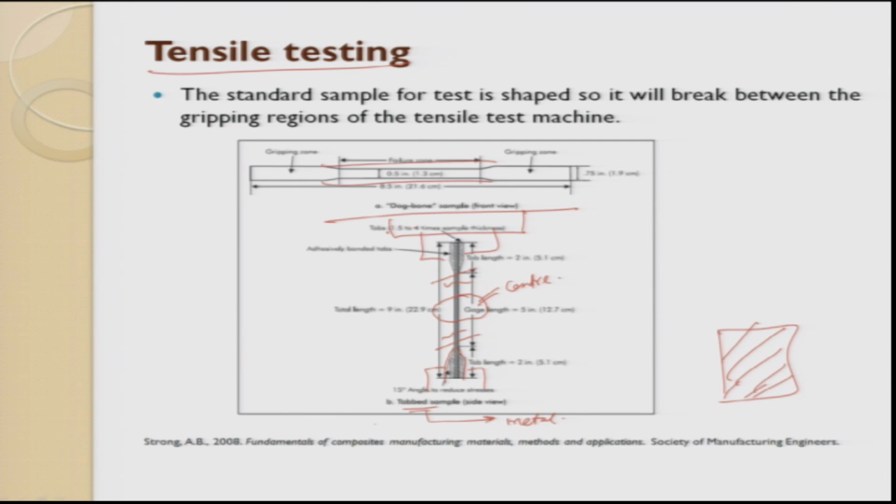The other way around is you use the chamber simultaneously and do the testing at the same time. Here the strain rates are important. If you choose an improper strain rate, then you will have strain hardening happening very fast. The strain hardening will lead to early failure. So, a proper choice of straining rate, that means the pulling rate, is very, very important.